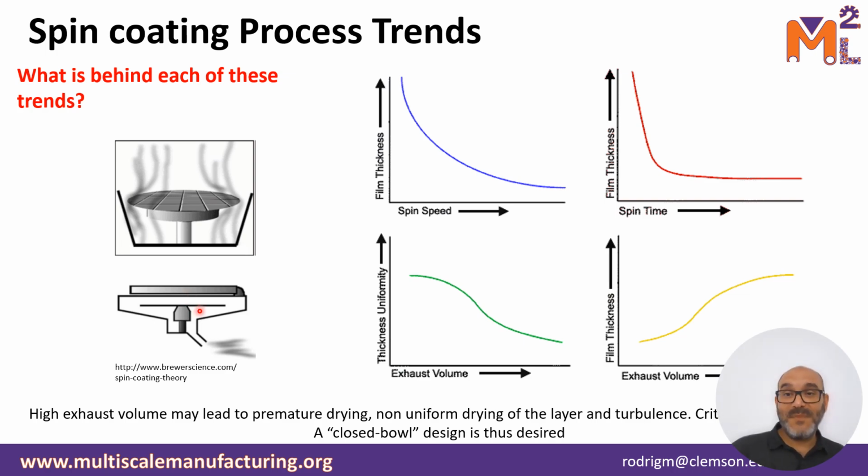That is good because the smaller the gradient, the lower the evaporation rate of the solvent, and that allows you to have similar consistency of the photoresist during your entire spin coating process.